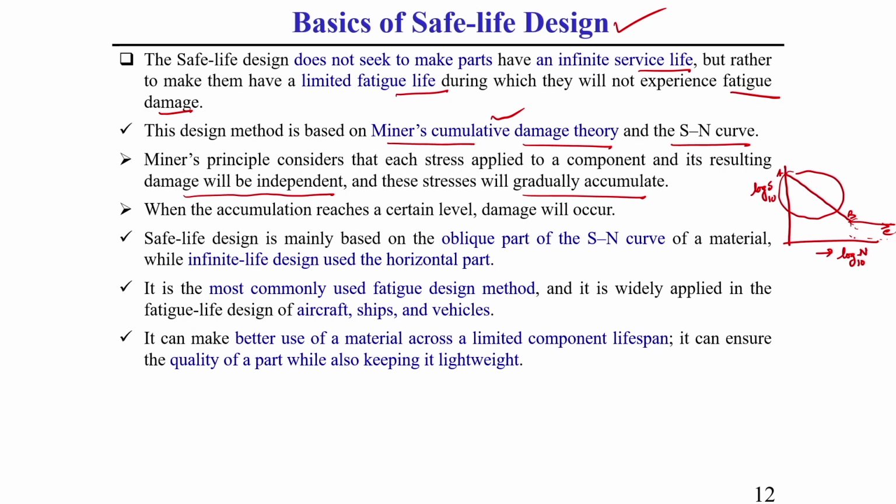Now, in Miner's rule you should also know that when the accumulation reaches a certain level, then damage will occur. So, what is this certain level? Everything in detail I will discuss subsequently. Now, this safe life method is the most commonly used fatigue design method and it is widely applied in the fatigue life design of aircraft, ships and vehicles. This you should keep in mind.